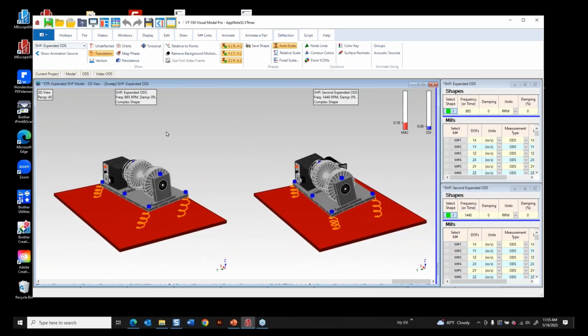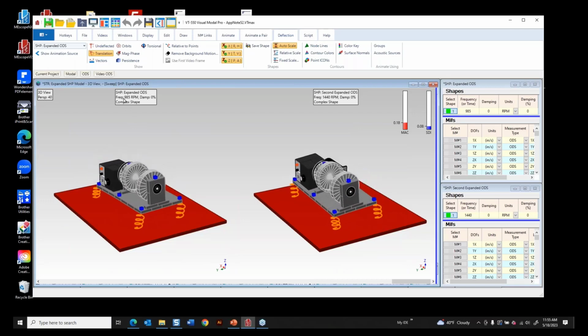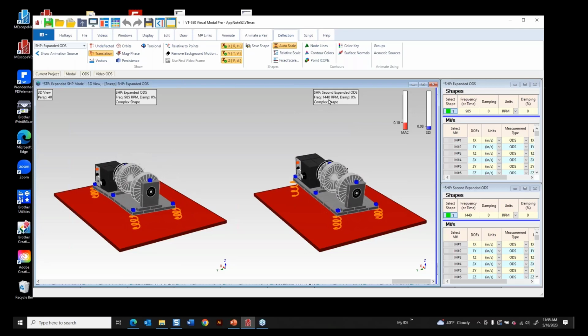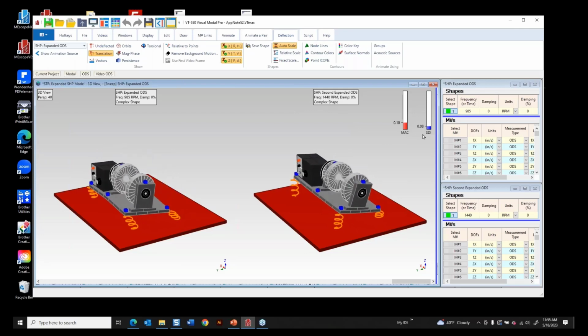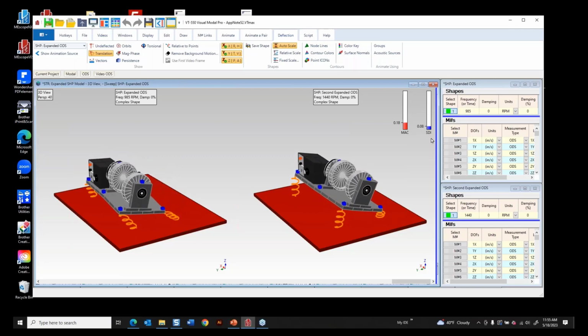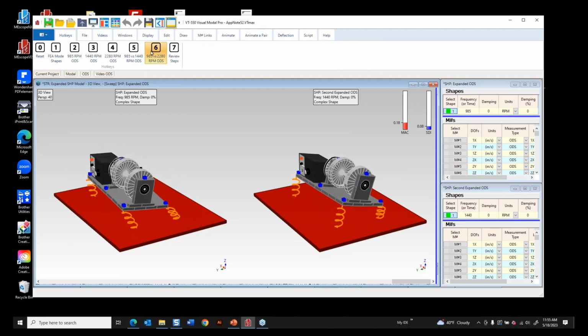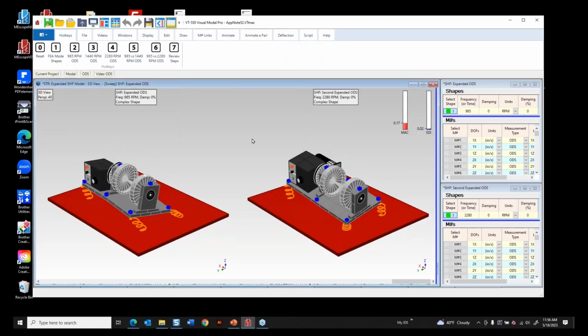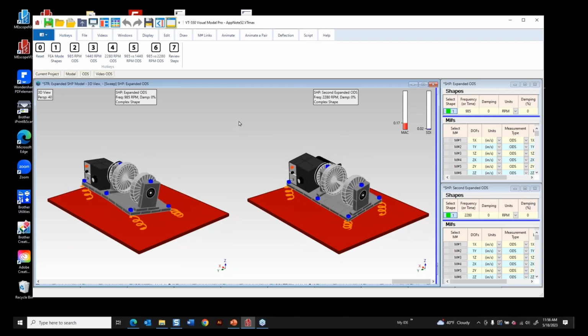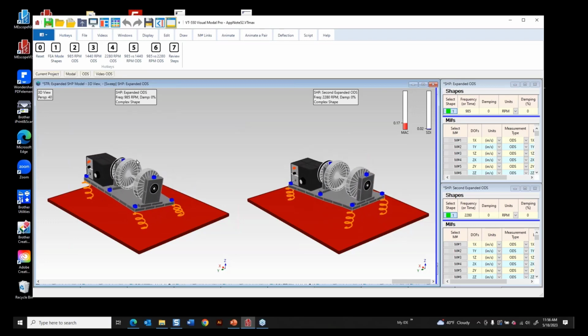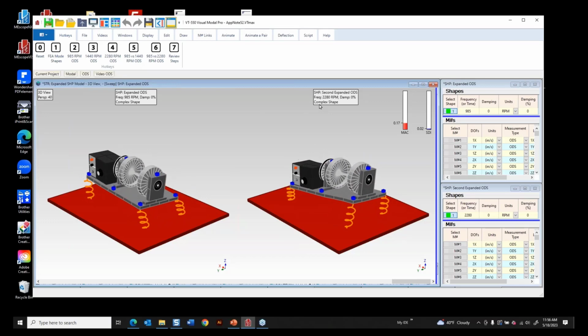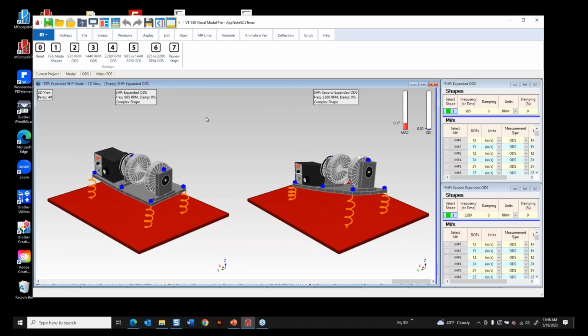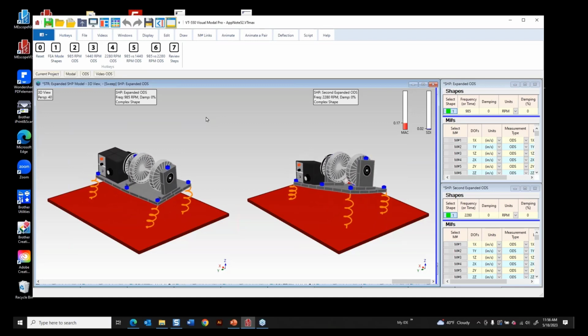Here's a comparison between the expanded ODS at 985 and the expanded at 1440. And you can see that they're drastically different. The values of MAC and SDI are very low. And one more, and then we're going to quit, Mark, and entertain some questions here. So here's how the ODS changes when, again, very poor correlation between those two ODSs. This is the 985 over here on the left and 2280 RPM on the right. Okay, let's wrap it up and answer any questions.